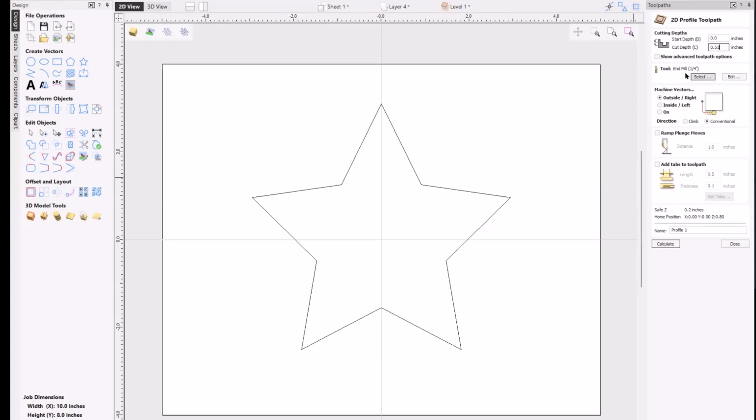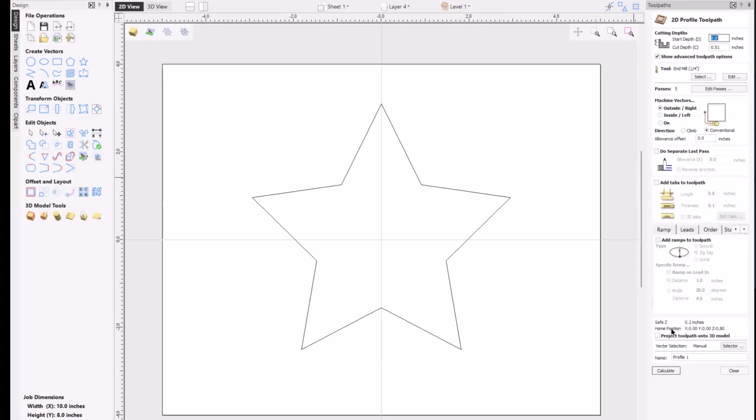As I mentioned earlier, pretty much the next thing you're going to look at, well, actually, let's step down here before I go to the select. I've got this checkbox here called Show Advanced Toolpath Options. It currently is not checked, so this list is fairly short. Every so often, people will say, well, where are the rest of the settings? And by checking that, it expands all the other more intermediate and advanced settings. So I usually run mine all the way open, but for some basic work, it's not required, but it's handy. Okay, so next, we're going to select the bit.